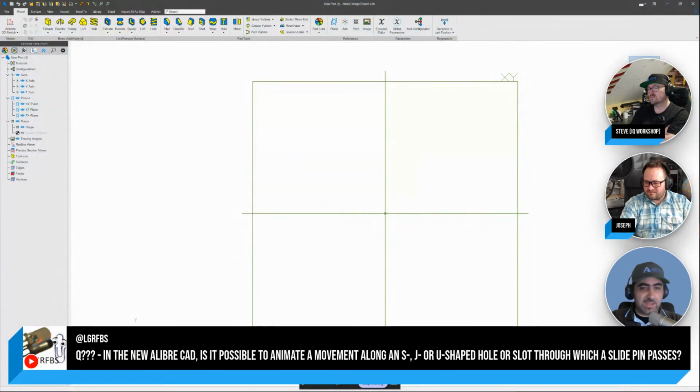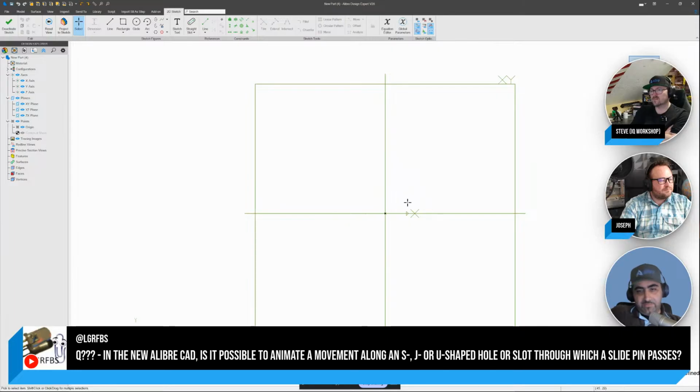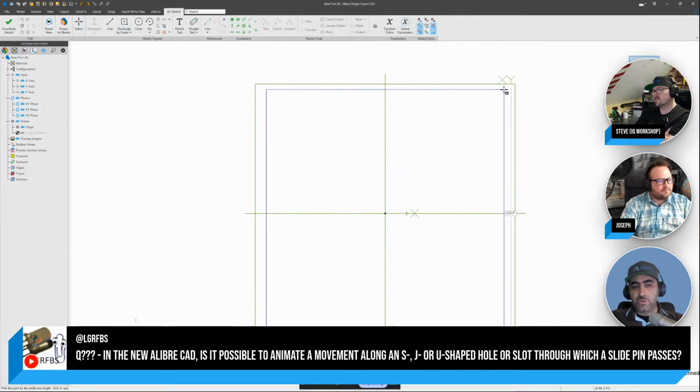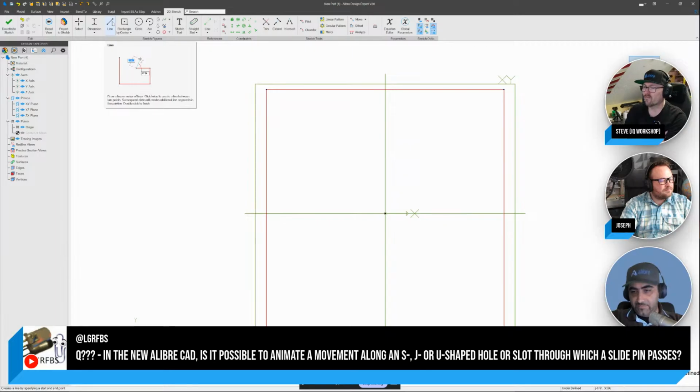That's a feature that Alibre already has, exporting a PNG. So what it does is it just drives the assembly for a small step. It grabs a PNG, a little more, grabs a PNG, and then makes a GIF out of it. But that is the closest to actually animating an assembly you can get in Alibre. You'll find that add-on in the forums.